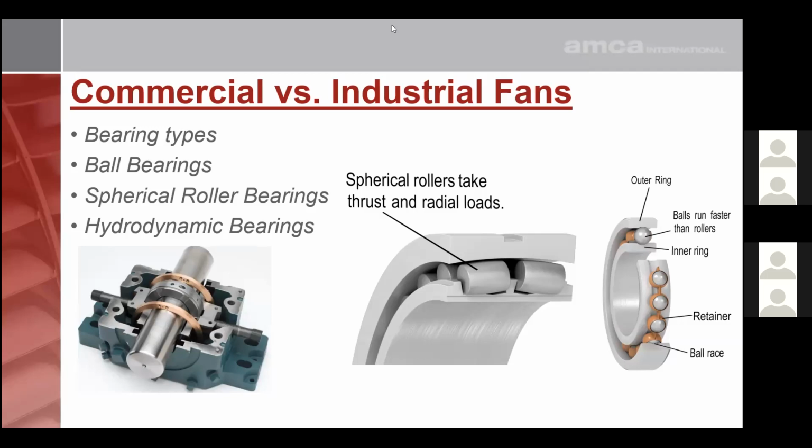The sleeve bearing life is ultimately reduced by the number of starts and stops, oil contamination, or any sort of excessive vibration in the fan. Sleeve bearings generate more heat than roller bearings, so oftentimes these bearings require some external cooling, whether it's water cooling or oil cooling. They also have a lower temperature limit because of the babbitt material in the liner of the bearing.